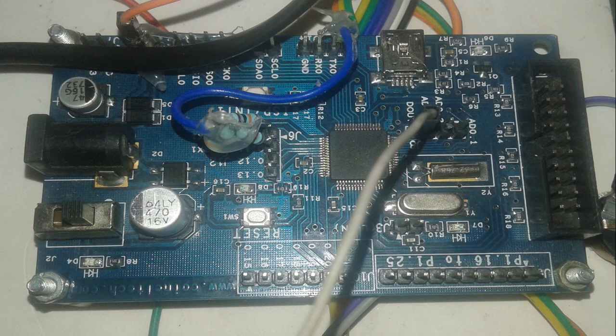4 types of waveforms are generated: sine, sawtooth, square and triangle. The input selection is given at the ADC, where the ADC receives the analog input and converts into digital. With respect to the input, the respective loop in the code is executed, and the respective loop's code generates a digital output which is taken from DAC, and the waveforms are displayed on the DSO-138 oscilloscope.